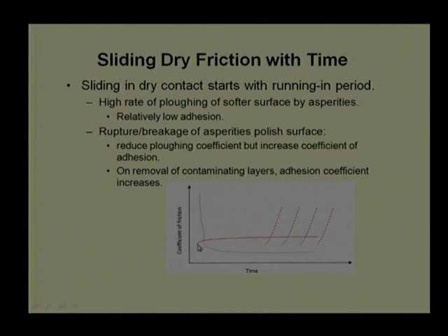This red line shows that adhesion will increase with the rupture of asperities, more asperities will come into contact, and there will be more and more junction formation. But junction formation and junction rupture will be a continuous process. So, finally, they have to come to one equilibrium position. That is why, when we average the blue line and red line, they will give us some steady behavior.